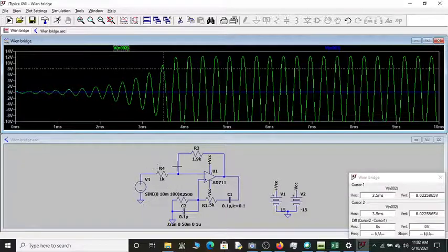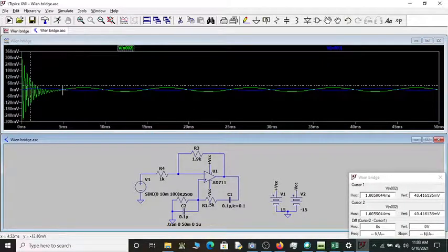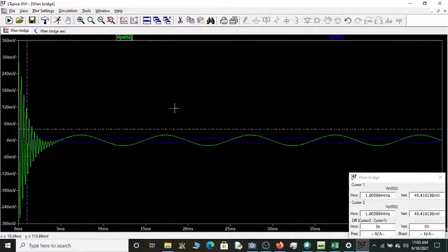Instead, it acts like an inverter, so it acts like an amplifier. The amplifier gain for this input voltage is minus 1.9. If you run it now, can you see this oscillation will die out, but you have this amplification. Whatever oscillation was initiated because of this will die out. Can you see this blue signal is being amplified by whatever gain is intended? This oscillation is dying out, whereas you have the amplification action happening.